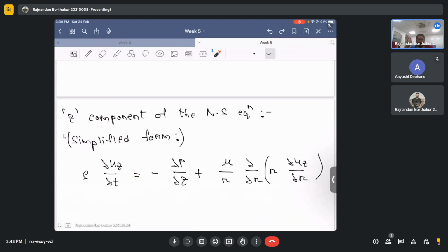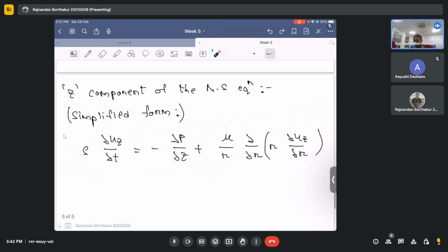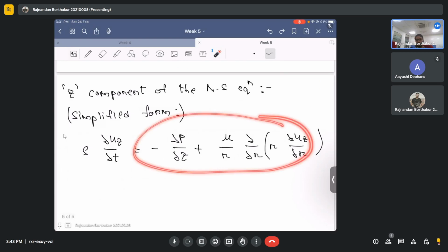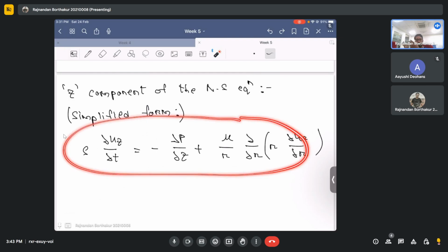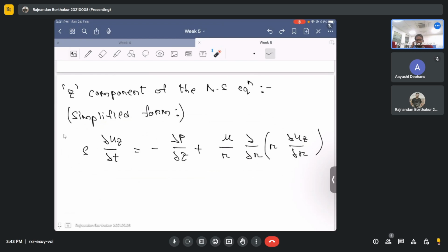Because if the pressure gradient is constant, then we will not have this unsteadiness. It's the Hagen-Poiseuille flow only. So if you just solve this, you'll basically get that Hagen-Poiseuille flow and that parabolic velocity profile that you know. However, the essence of adding that oscillatory term is what leads to solving a PDE, which we earlier solved as an ODE in the Hagen-Poiseuille problem. So I hope the difference is clear this time.